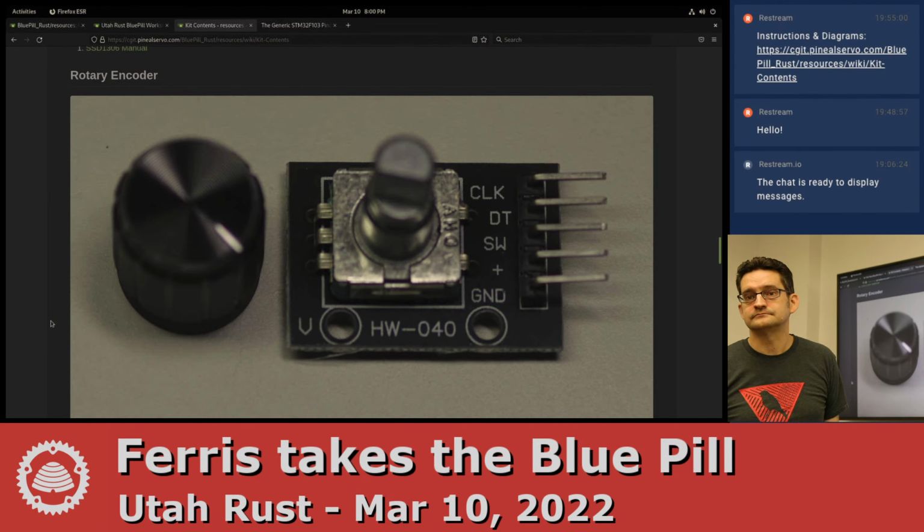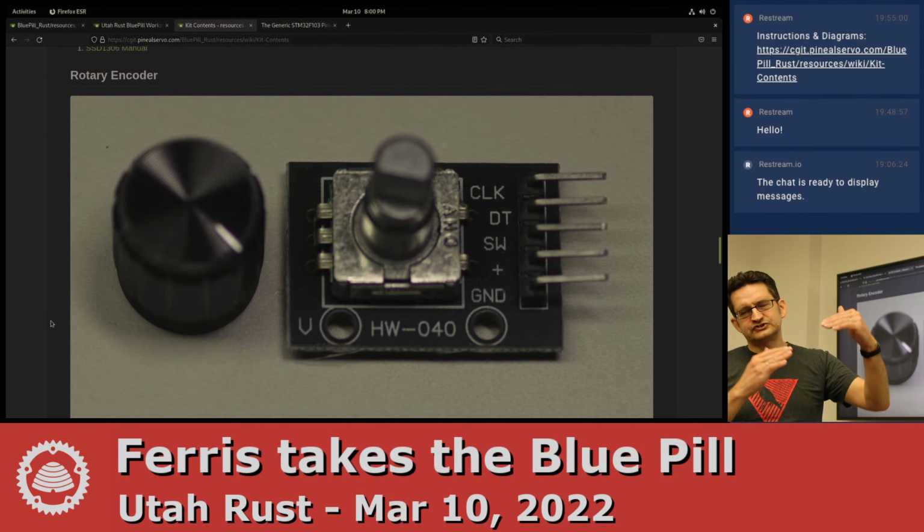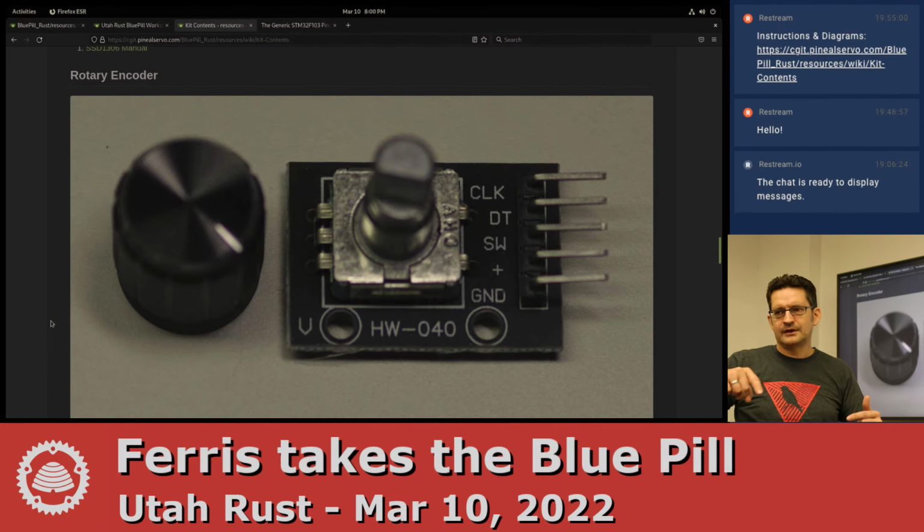These are the kinds of knobs that you can just keep turning forever. They don't have end stops, and so you can turn them 360 degrees many times. They work on the principle of having two switch contacts that are sweeping across some interrupted contact traces, and so they flip on and off out of phase with one another.